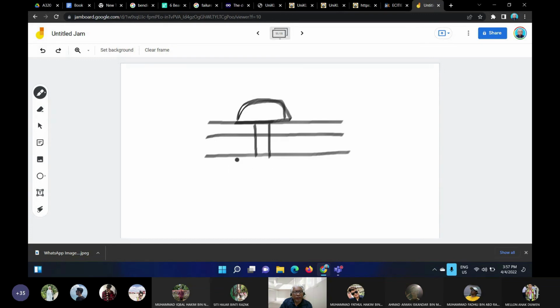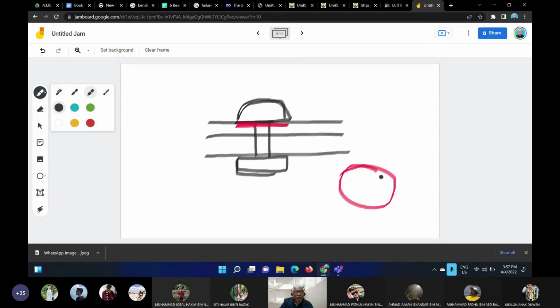This is a formed head after the backing bar. So we need to consider this area here. If we look at the area from the top, it is round, and then you have the rivets. So you need to consider shear off. This one is shearing off.